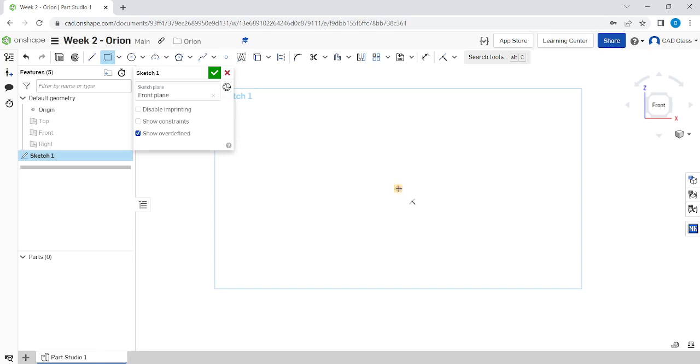That means that I am going to create what's called a coincident constraint. Not super important what that means, but you can just think of it as I'm going to attach the corner point of the rectangle to the origin point. So if I click while this little square box shows up, it looks like the rectangle is attached to that corner, which is good. I can go out here and click again and then press escape. You'll notice this dot is black, this line is black, and this line is black. So if I click and drag on these, I can't move any of them. I can still move these corners, but this corner is locked to the origin.